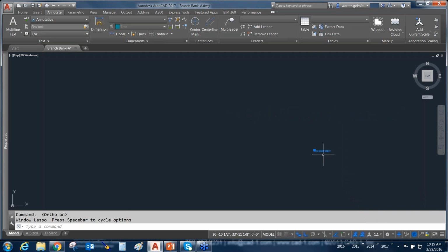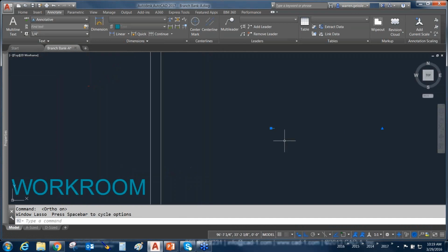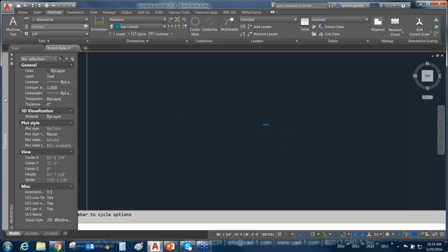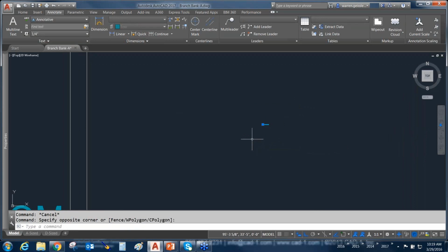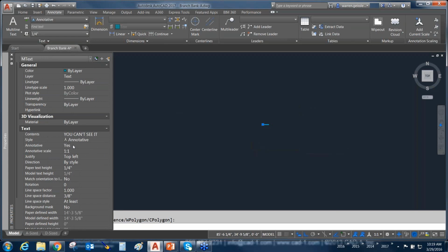We're not going to print drawings at 1:1. So how do I fix this? Well, there's a couple of ways to fix annotation inside your current drawing. Method number one is you get to use the AutoCAD properties window, which I've got anchored over on the left-hand side of my screen. If I grab text inside my drawing and I come over to the properties window, the program is going to be telling me, pull this out a little bit, that yes, it is in fact annotative.